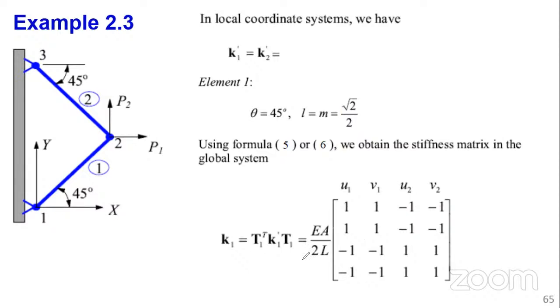It's as simple as ABC. So this is just reminding you of how we obtained the global stiffness matrix. This was a formula, but remember we have already derived it. So you don't have to go from first principles to derive this part, because you already derived what K global is, which is equal to EA over L, then L squared, LM, and so on and so forth. So you do this for K1. The difference is that different elements will be oriented in different directions. So the angles will be varying, so the direction cosines will be different.